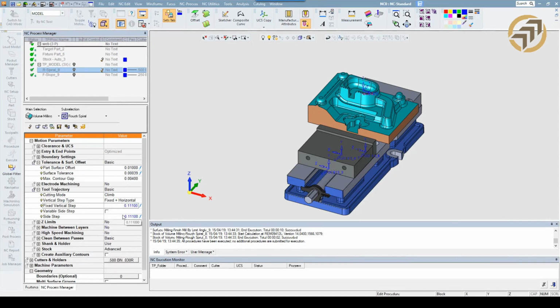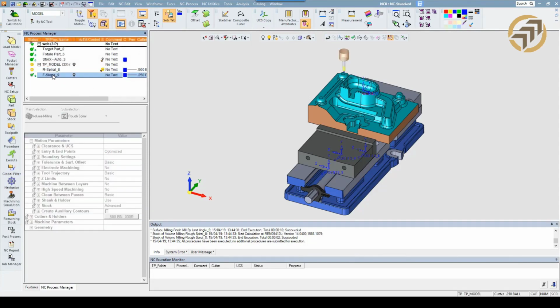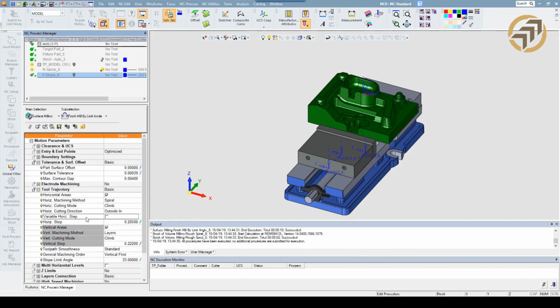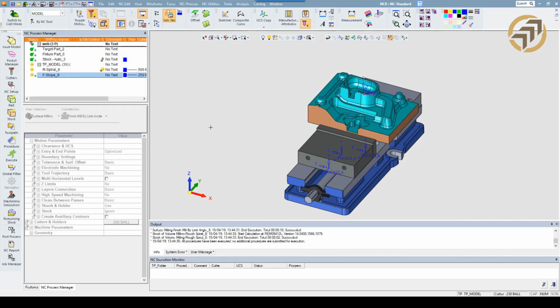Now it's going to adjust the speeds and feeds right to that new material. You can just save and close those. You can do the same thing here. And that's all updated. So now you don't have to worry about fat fingering a number or pulling in a whole new cutter library and reselecting cutters again.